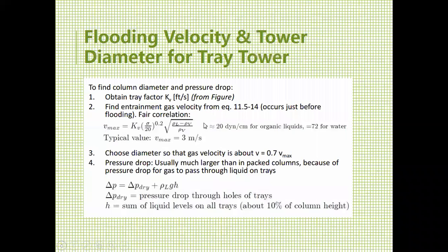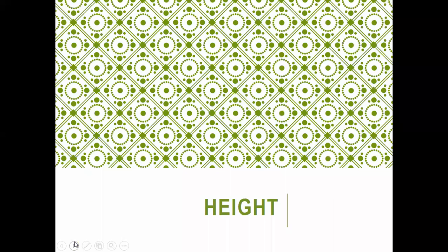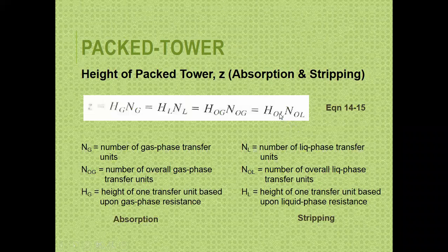A little bit simpler, actually a lot simpler than the procedure for pack towers, because right away you'll be able to determine here the linear velocity, the maximum linear velocity when the column is already flooded, your tray column that is. Okay, now for the column height, you will be using a lot of formulas depending on what data you can work on in terms of the column height. So these particular formulas that I have written is found in this section of your handbook.